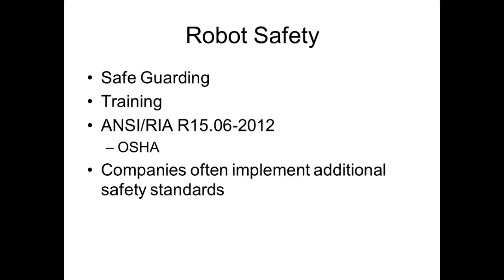And is that law? No. It's only law if it's adopted. OSHA has adopted NFPA 70, and you can adopt that every year, but they have not adopted 70E. But if you follow 70E, you meet the requirements of OSHA 1910, which is their big book. It has all their safety in there for just about every type of thing you can talk about.